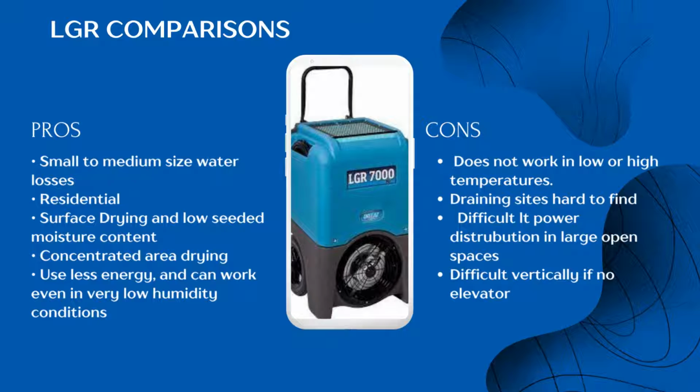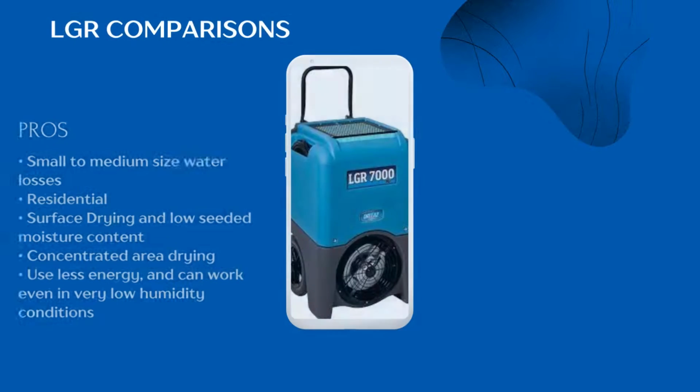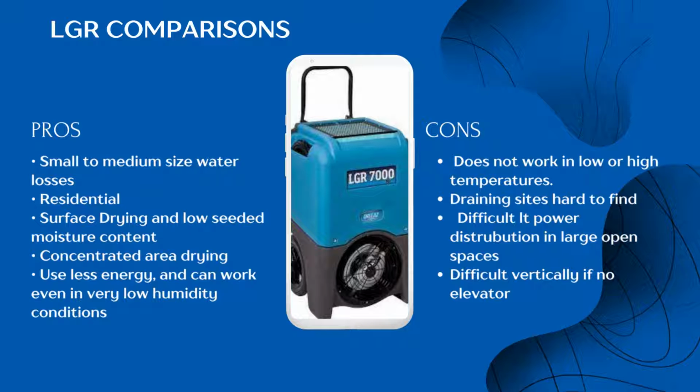These larger dehumidifiers use a lot of power. And once again, in commercial buildings, unlike residential, there's really not a code on how often you put a plug. They just sort of put them where they want to and wire them in. And so sometimes you will get a big office area that has a few plugs, but you'll find out they're designed to run computers and that you may not be able to get enough electricity to power those. So you may have to go with power distribution.